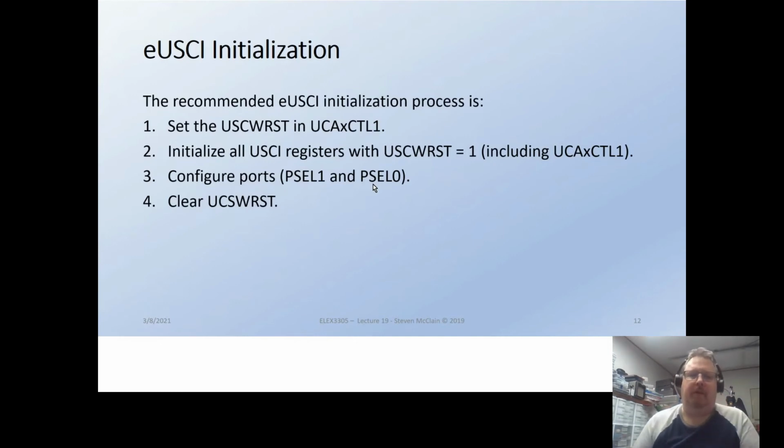So I'm just thinking for the ADC one, like we had to initialize the ports on a separate... Oh well, with the ADC one, you were kind of cheating on changing the channel for doing multiple channels, and you wouldn't necessarily do it that way in a real product. Yeah. Right. It's a lot of overhead and it's a little clunky. It's fine for doing a joystick, and you could use it for a joystick forever. It wouldn't matter. Nobody's gonna notice you used extra clock cycles.